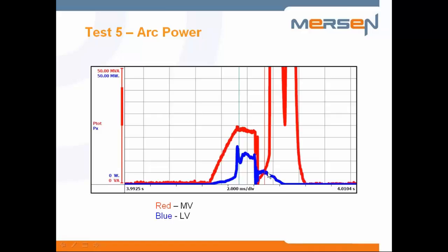But also notice there's some additional energy under this power that comes from energy stored in the windings of the transformer. So even though the grounding switch has put 0 volts on the primary, there's still energy that needs to be bled off, although it's very little. Thing to note on the primary, the power being delivered is a little greater, but notice these large excursions. That's the arc energy within the medium voltage fuse, and you can see it hits a very, very high level. This would be the first 2 fuses clearing, and this would be that third fuse that cleared.